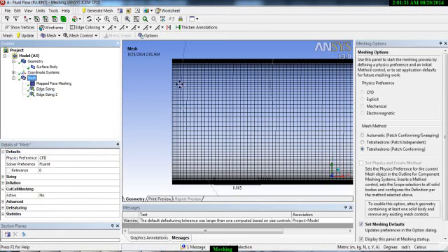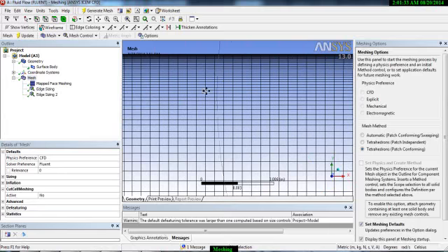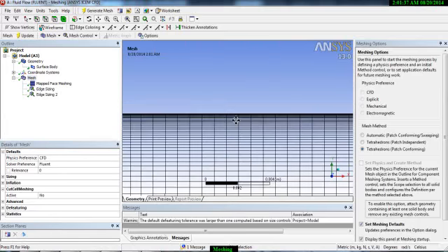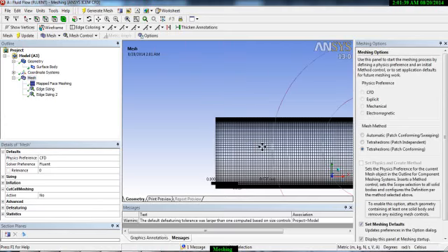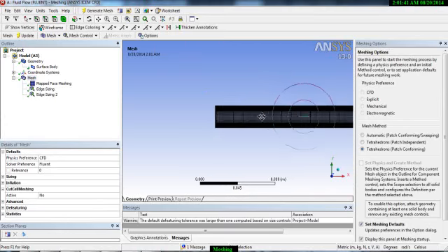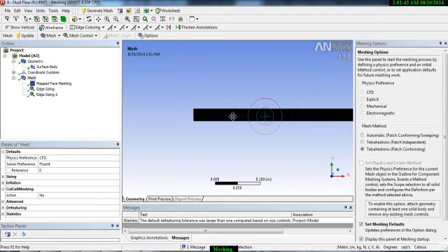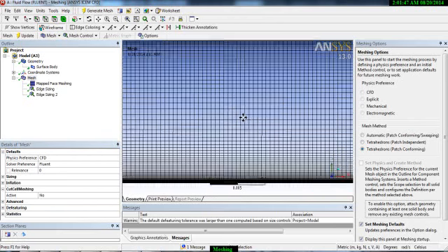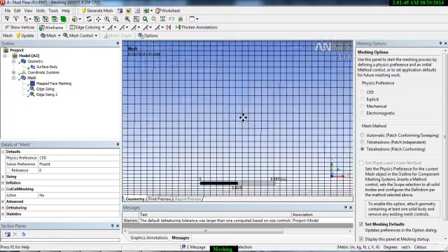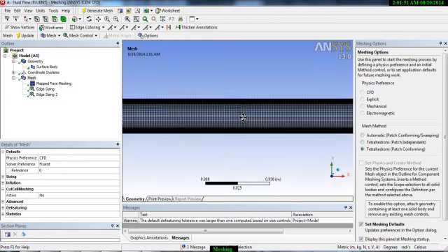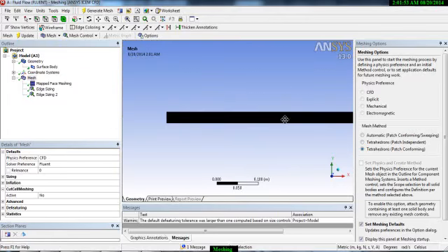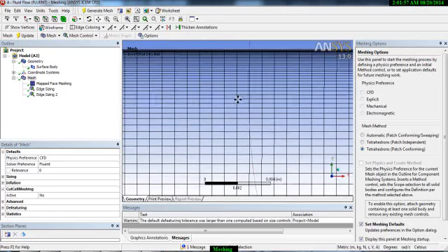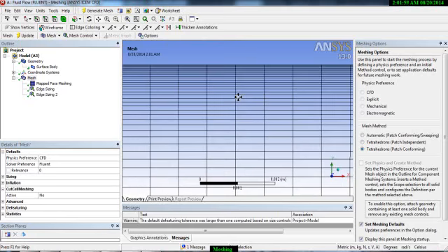In general we keep the maximum number of nodes close to the wall so that we can see the boundary layer more easily, and we can resolve the change of velocity, pressure and temperature more easily. So you can play with this bias setup and number of mesh to see the changes.